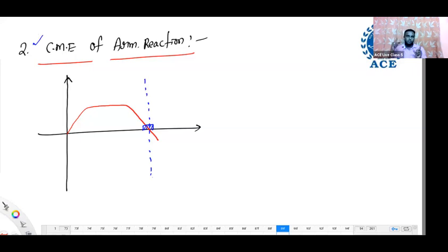Due to that, distortion. So because of this, now see, this is our resultant flux during armature reaction. What is that resultant flux? If you remember, it is not becoming 0 along the brush axis. Yesterday's diagram I am drawing again here. Okay. This resultant flux is not becoming 0 along the brush axis. Now there is some flux or not? Yes.